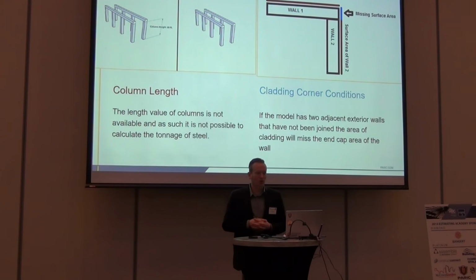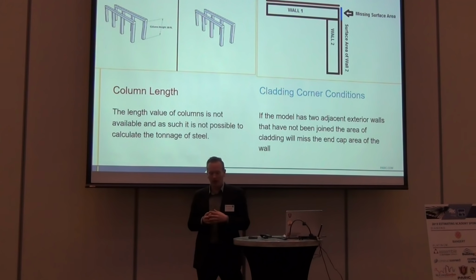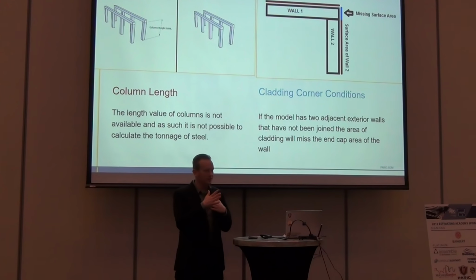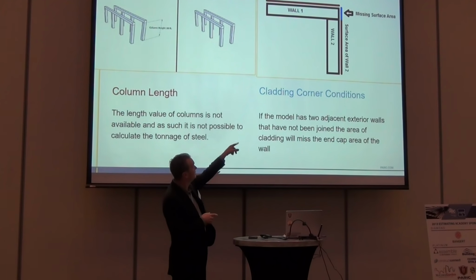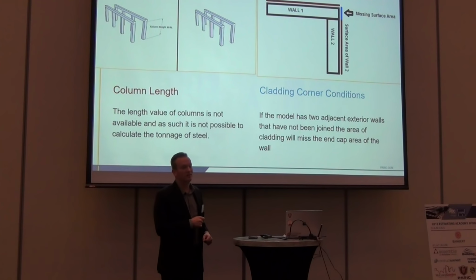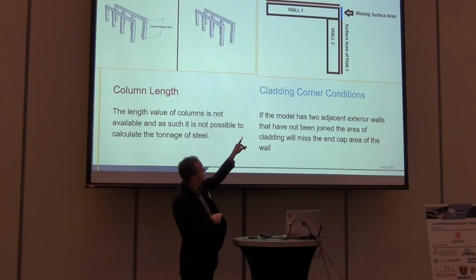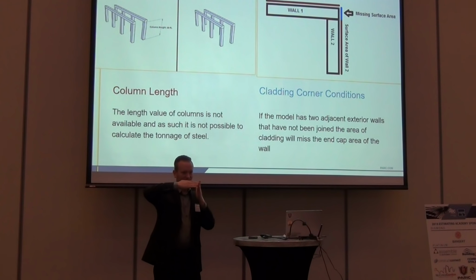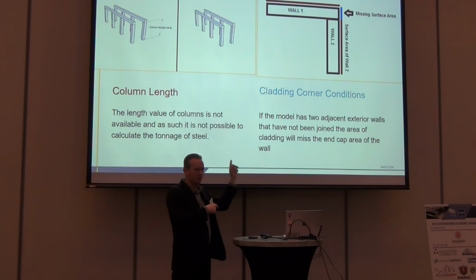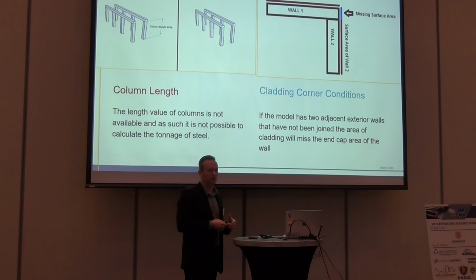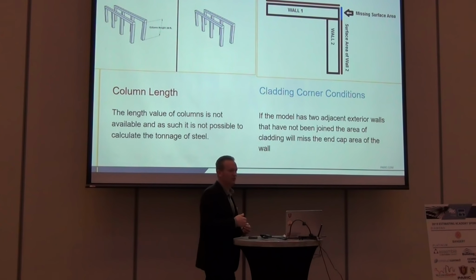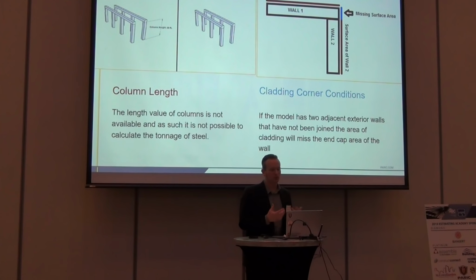The other thing is with walls. So the way that an architect may model two walls and how they come together at a corner or at a T impacts the amount of quantity that you actually get. So up here in the top right, you'll be missing surface area where the two walls came together like this, and they weren't actually mitered together. So you'll be missing 9 square foot on a partition wall 400 times. And all of a sudden, you've got a gap. So this is where we have challenges.